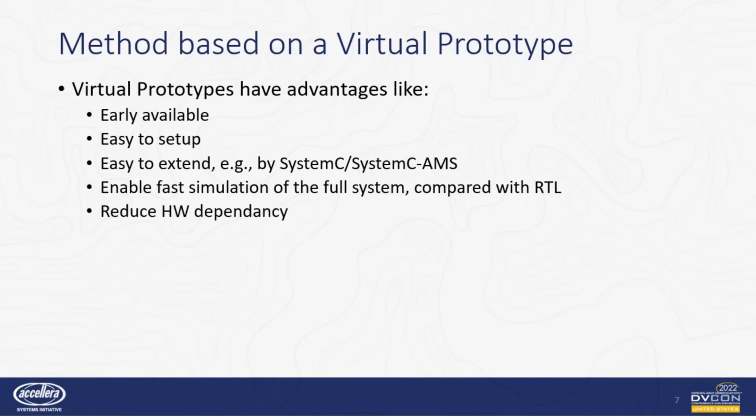The nature of the virtual prototype extends the so-called prototype test bench for the software development team. With a virtual prototype, the hardware dependency almost vanishes in the first stages of the project to prove the viability of the concept. A virtual prototype that allows interdomain simulation represents a support tool for software development and updates in a product lifecycle. In this development flow, they can even support full stack software development.